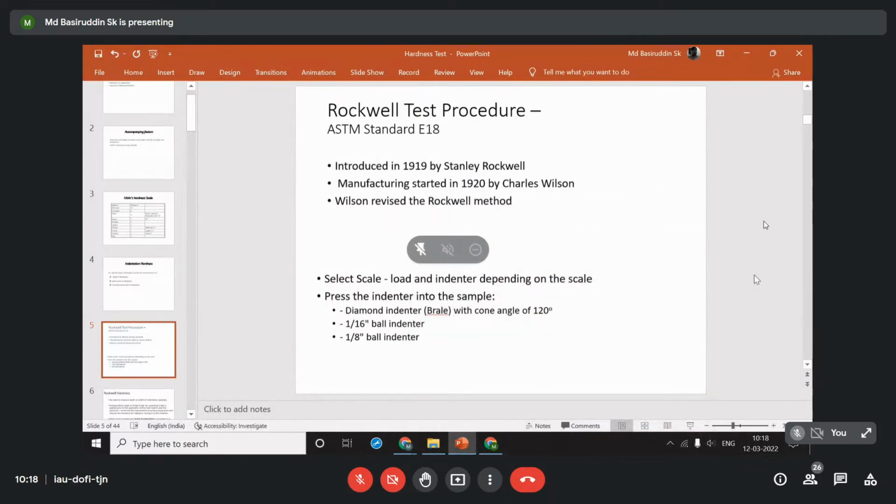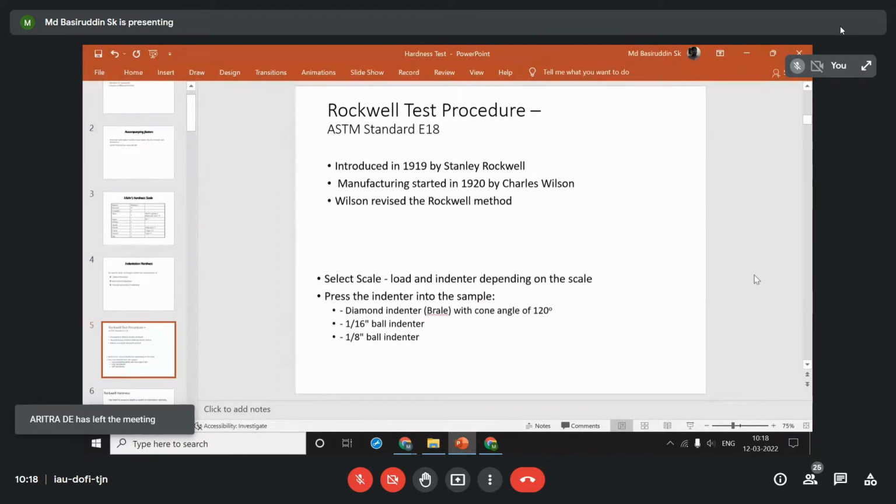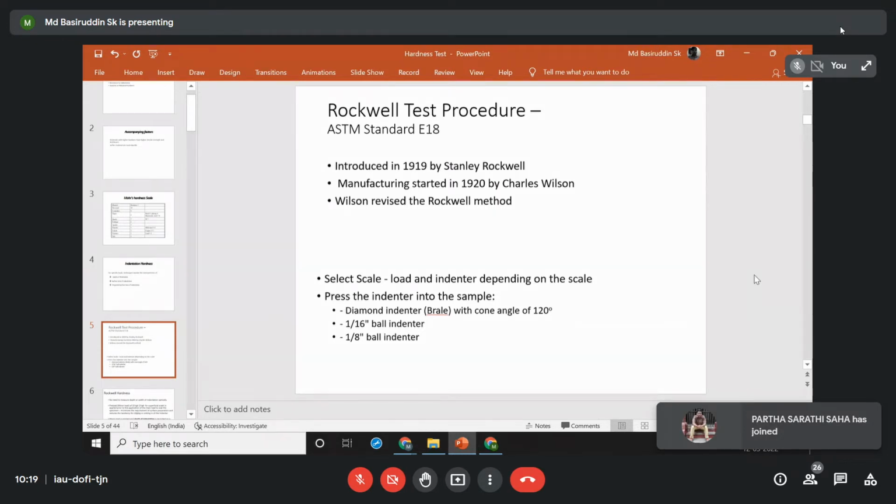Okay, so previously we were discussing hardness testing to evaluate hardness, that is, the resistance of a material to localized deformation. We discussed the different types of hardness: we can do the scratch test, and we can do the indentation hardness test statically or dynamically. That means we can apply a dynamic load that depends on time, or keep a fixed load, and based on that we can see how the material deforms depending on the type of load or loading pattern.